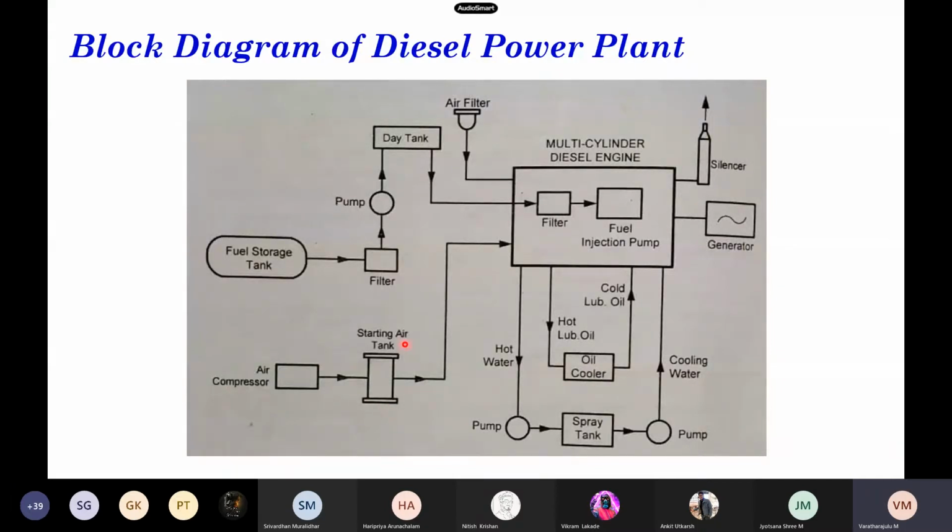And as I said earlier, the function of this system is to start the engine from cold by supplying compressed air. And the second system is the fuel system. The pump draws diesel from the fuel storage tank and supplies it into the small day tank through the filters.